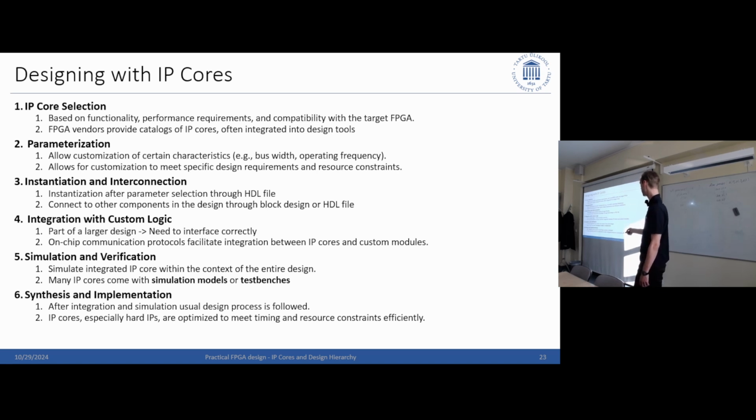algorithms or whatever, you will have to give the data in, and those kinds of things you have to do manually. Also, older devices and older tools do not necessarily support automatic connection, so you have to write your HDL wrapper on top and connect everything to each other. Exactly, so you also have to do on-chip communication to get the data in. It usually uses standard communication interfaces. We're going to have a lecture on that, but I had to start either with interfaces or IP cores. Today we have IP cores, and later we have interfaces.